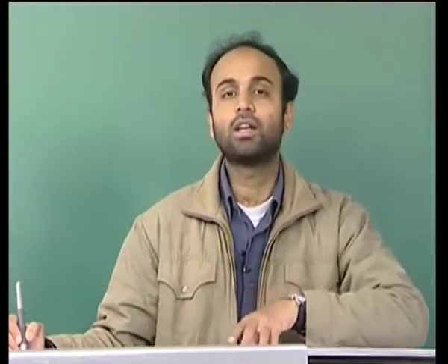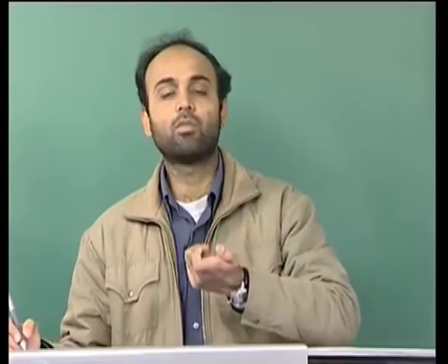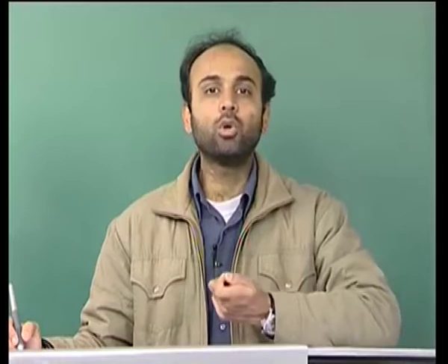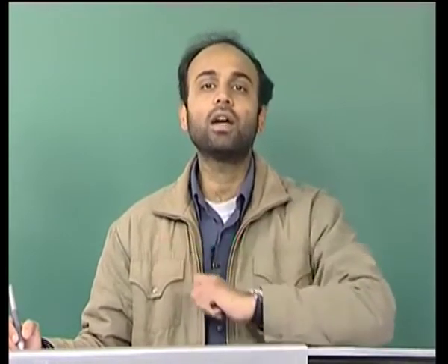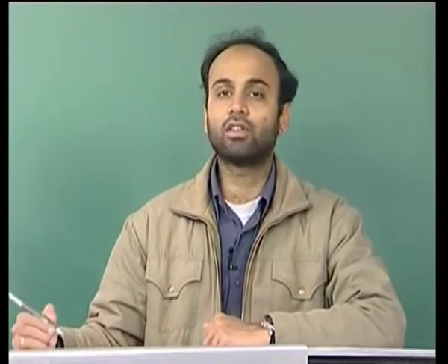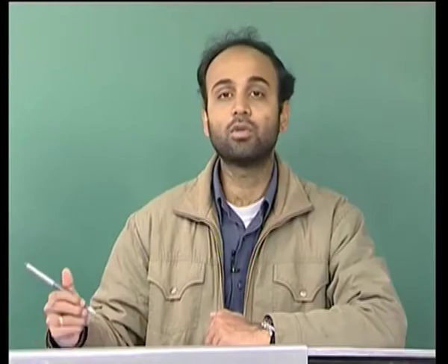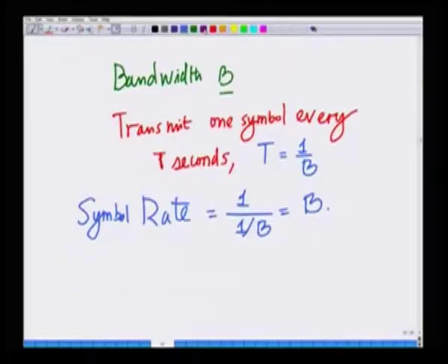All right, and traditionally what you do is you have this baseband, you modulate symbols on the baseband, employ a single carrier to modulate this stream and transmit it in the allocated passband bandwidth. All right, so this is the conventional communication system which is known as single carrier communication. This is a single carrier communication system.